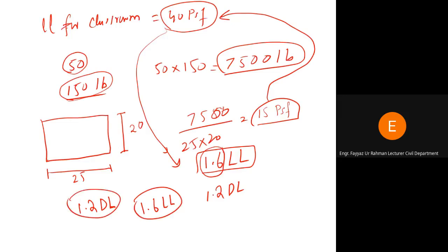जो आपने अभी पूछा पिछले स्लाइड में लोड फैक्टर के बारे में, तो these are those load factors. Because there is less variation expected in the dead load, that is why the load factor for dead load is less than that for the live load.